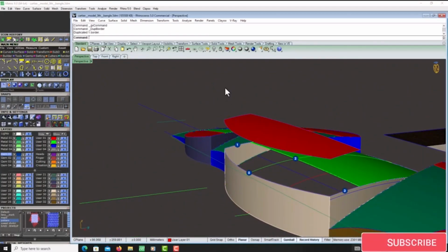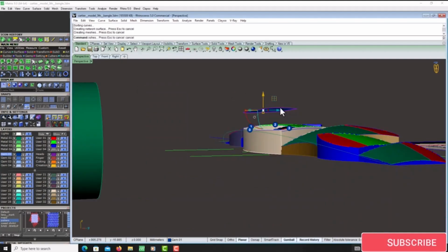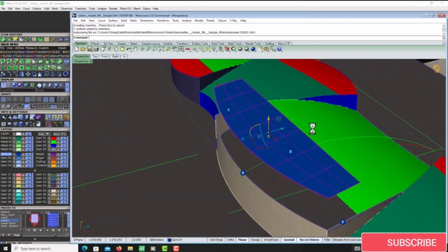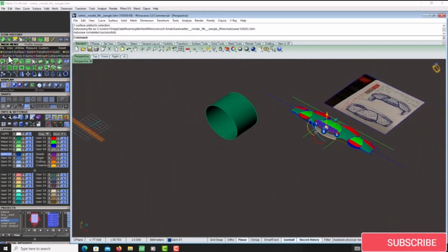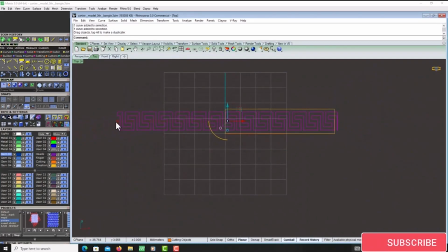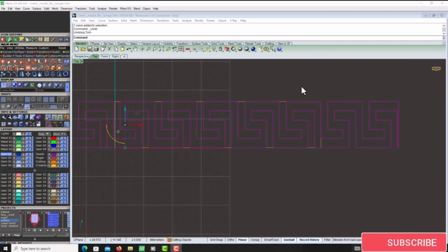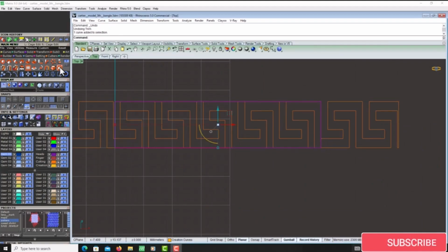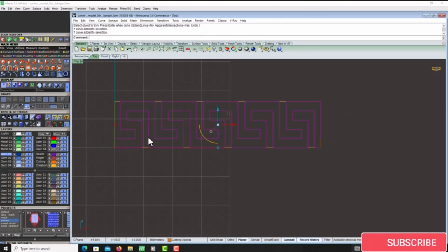It means you choose the Versace pattern and your surface UV curve, and then click on apply curve, and then click on a surface, then the Versace pattern is applied to your surface. We are moving and changing the dimension of the Versace pattern to our orange curve. The orange curve is our surface UV curve.